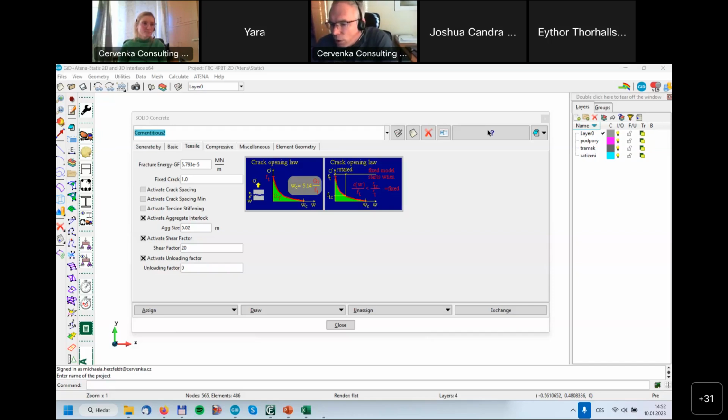And then there was a question from Kunze. We were speaking about a short fiber reinforced, classically steel reinforced girder. For which fiber types is the model applicable? Because this makes a difference: steel, carbon, polymer, etc. For different types or shapes of softening diagram, it is definitely applicable.